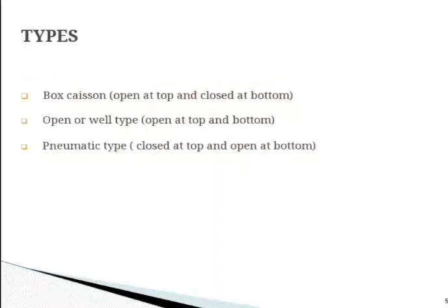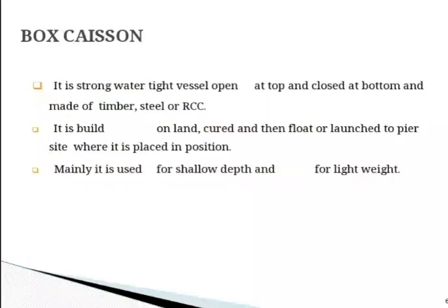Types of caisson. Box caisson, which is open at top and closed at the bottom. Then open or well type, which is open at top and bottom, and pneumatic type caisson, closed at top and open at bottom.